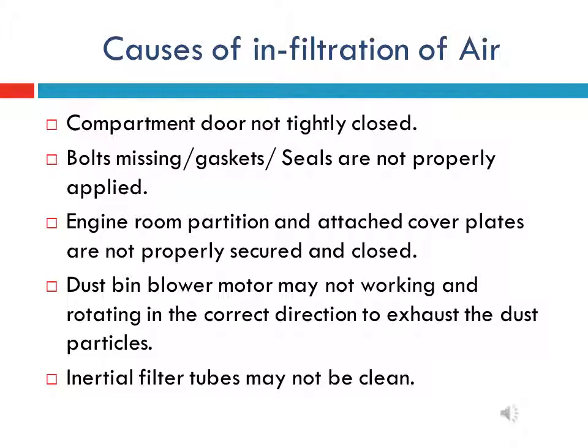Third, as given, in the engine room the partitions should be proper. If they are not properly secured, there may be the possibility of unfiltered air entering the air compartment. The dustbin blower provided in the air compartment should work properly, otherwise it may not suck the dust from the cyclonic filter, and in this case the dirty air will enter.